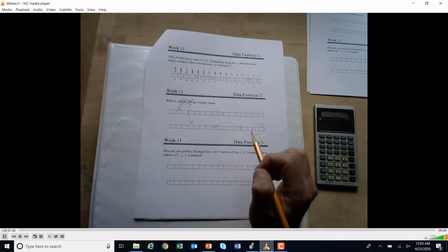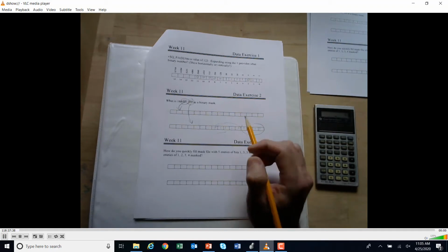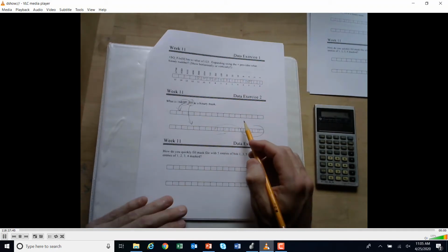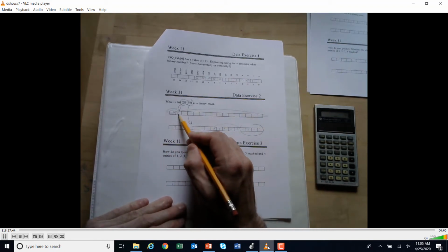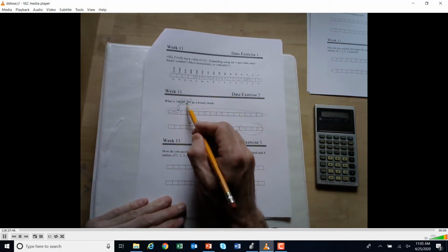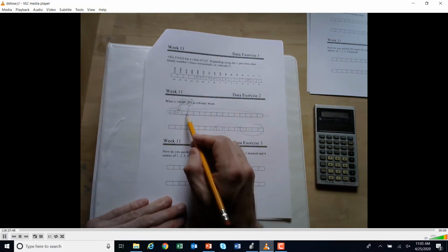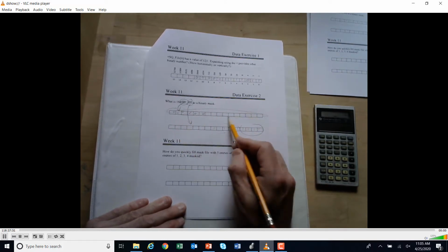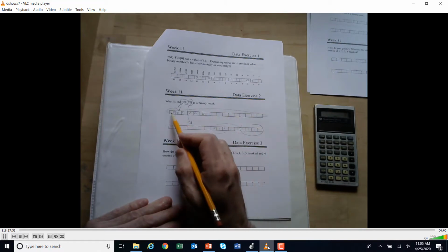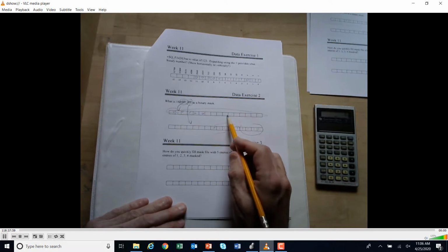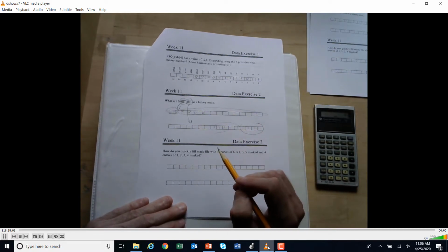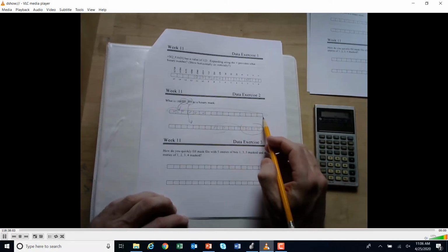So if we're only using an int and not a dint, then a lot of times we can take the second part of this and just mask it off with all zeros. So we could have gone 0, 0, 0, 0, and then FFFF. That means that we pretty much take out the first part of this word, and we turn it into an int, because we're not going to allow any data to pass through it, even though it does have additional data. If we masked it, it wouldn't be coming through.